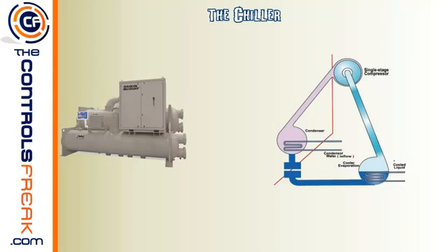One other thing to note about chillers is that in these barrels that you see here, there are many different bolts that come across here that seal up the 2 ends of this barrel. Inside the main portion of this barrel, these water lines that you see here are actually long tubes that run the full length of the barrels. So if you ever hear of somebody saying they were changing out tubes or they have dead tubes in the barrels, these are those tubes, and there are many of them. I've seen some chiller barrels that had literally 100 or more inside the chiller barrel.